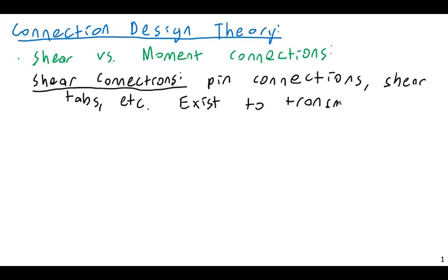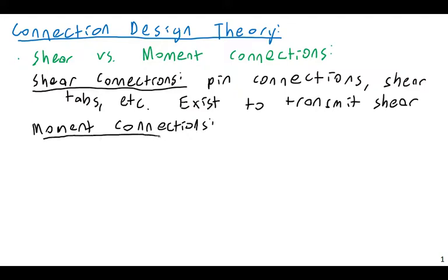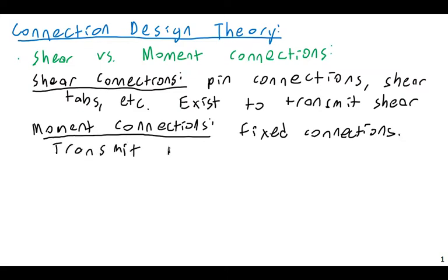These exist primarily to transmit shear. And I will talk about this later in terms of what this means for individual elements. Moment connections are referred to either as moment connections or also fixed connections. And of course, they transmit moment between members.